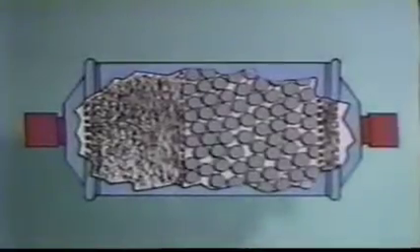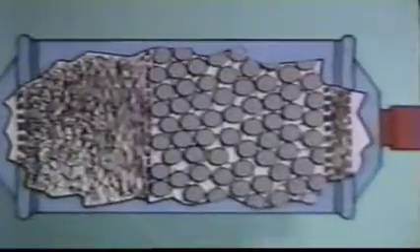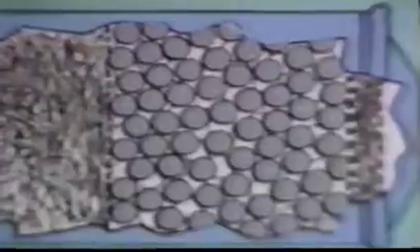After passing through the filter, the refrigerant will flow through the drying element. In quality dryers, this material, known as desiccant, collects moisture through a process called adsorption. In adsorption, water, as an example, is collected and held on the microscopic internal surfaces of the desiccant material. This internal surface area is 10,000 to 100,000 times greater than the actual surface area on the outside of the desiccant bead. The desiccant will collect wax and acids in much the same way.